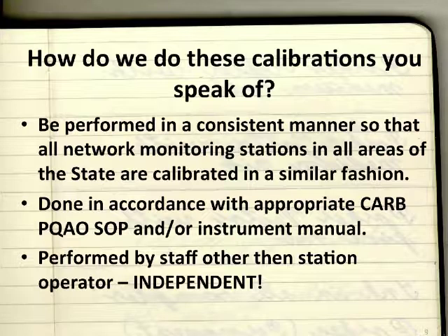And also, they should be performed by someone other than the station operator. This was a discussion point that came up at our training last week down at South Coast, is if it should be a different person than the station operator doing the calibrations. We want the calibrations to be as independent as possible. So as an operator calibrating your own site, that's almost like yourself grading your own midterm or something like that. So we want it to be as independent a process as possible.